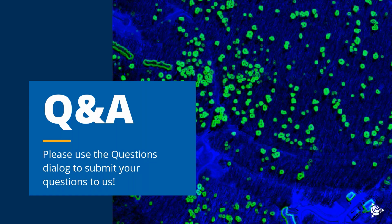Well, that's funny that I was asked, because I did. The imagery wasn't perfect. When I looked at the whole study area I worked in, especially with the high relief, it was a very mountainous region. So there were image blurs and shadows and seam lines that weren't perfect. When I ran creating candidate objects and classifying, I was picking up some of these error areas, and I think that contributed to some of my results.